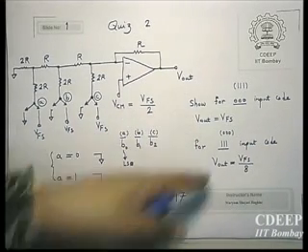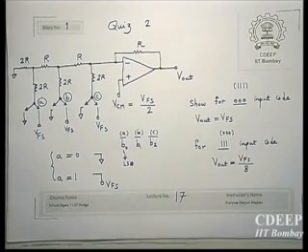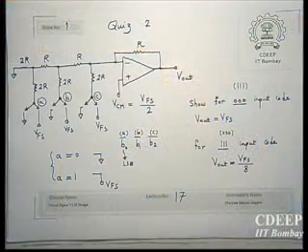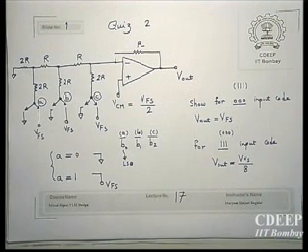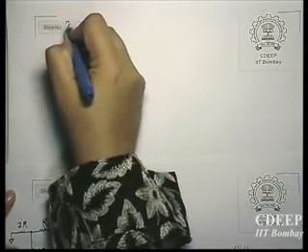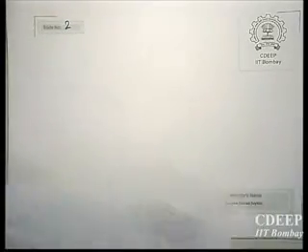So the only thing you see here is a shift of V full scale by 8 to the right. It means that for all 0 you will get V full scale by 8 instead of 0. For all 1 you will get V full scale. That is because we don't have any negative voltage here. But still your complete range is covered. And to use this analysis, it is good to always simplify the circuit. Therefore, it makes it very easy if you use this.